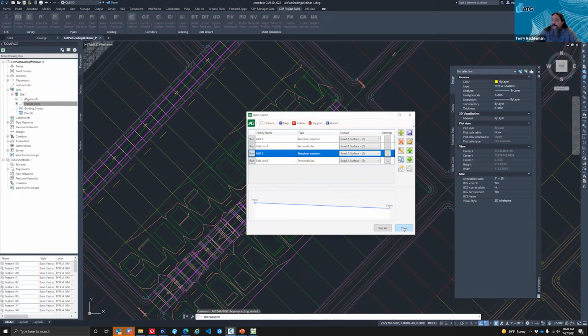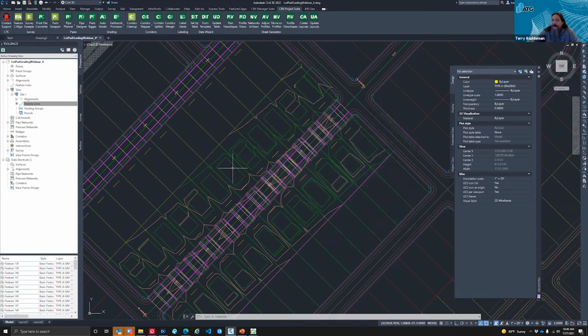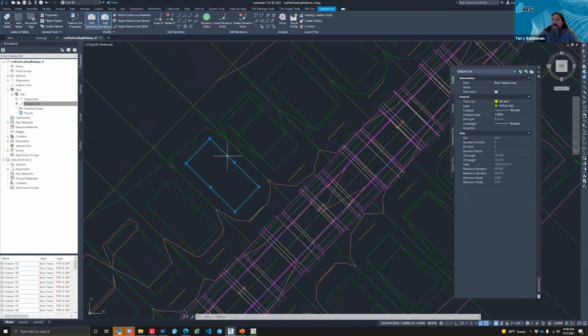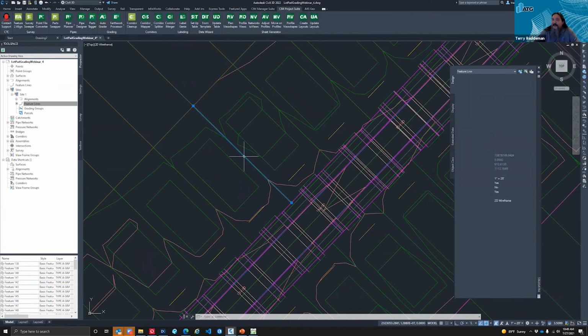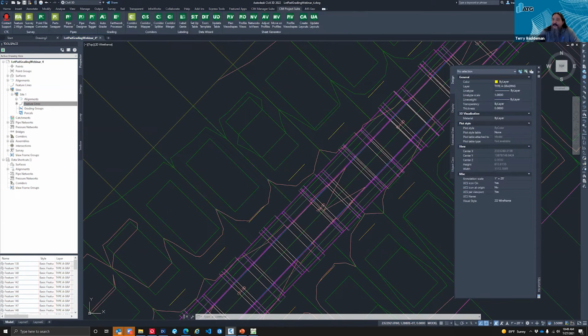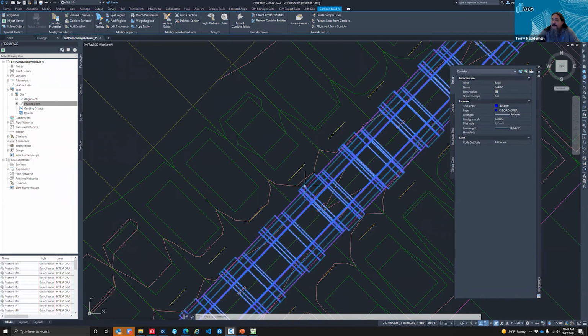All right, we'll go ahead and close that. And so now we have our pad B. If we look at our pads here, our pad is high point in the middle, sloping down on each side. If we look at our lot line here, we just have a straight 2% slope going back. And I'm going to save this again, and then we'll view this one more time in 3D, and then we'll look at some ways we can label to check our design.